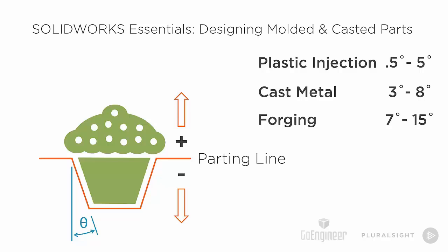These are not absolute values. They're ranges. They're rules of thumb. They're areas for you to start with whenever you're trying to design your geometry that's related to tapers and drafts. So in the next few examples, you're going to see us employ the draft angle. Remember that that's based off of the vertical. We're going to apply this angle of theta in our draft as we create features. So let's get started, hop into SOLIDWORKS, and get to creating some geometry.